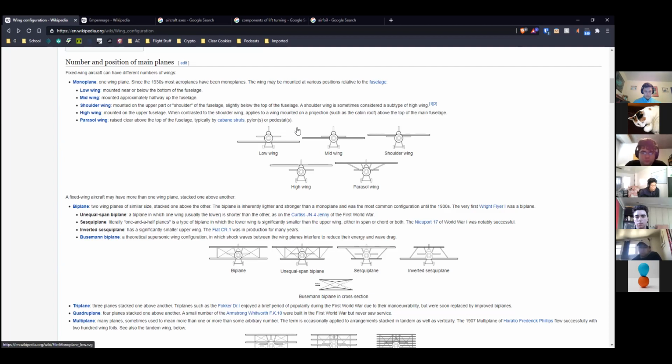So you can think about where you put the fuselage as how you want it to be supported by the wing. If you sit the fuselage on top of the wing, aka a low wing, you're balancing that mass from the fuselage on top of the wing, which isn't that big a problem, but it means a lot of planes like this will have dihedral, which we'll see later, because it helps create natural stability. If you're balancing it like that and you have negative stability, for example, it would have a tendency to roll by itself more easily,